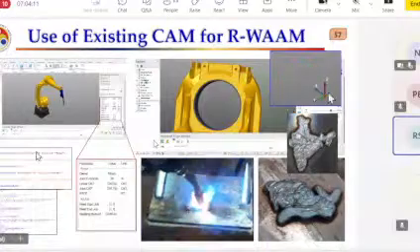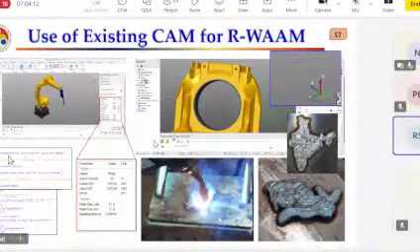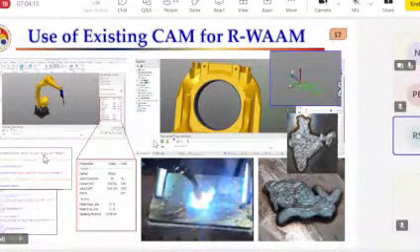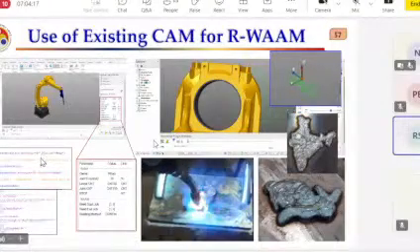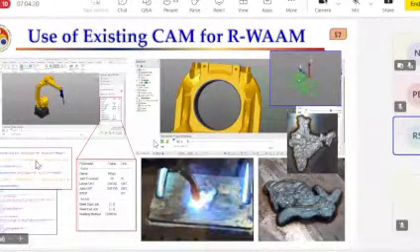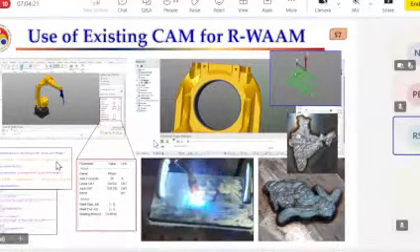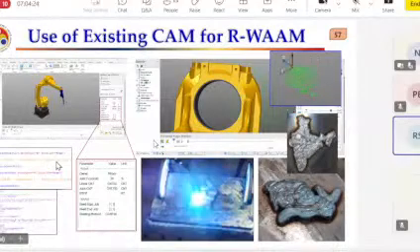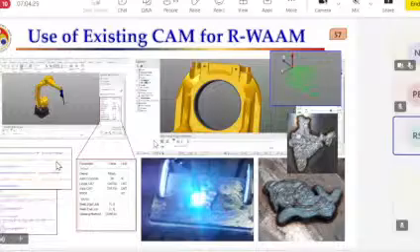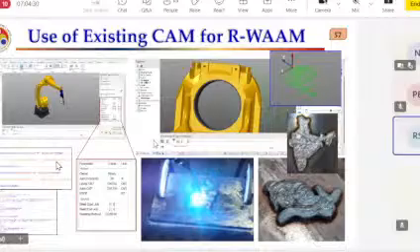And we even need to modify the post processor as well. Wherever there is a cutting move, like the feed move, we can put one line with the command to start deposition.